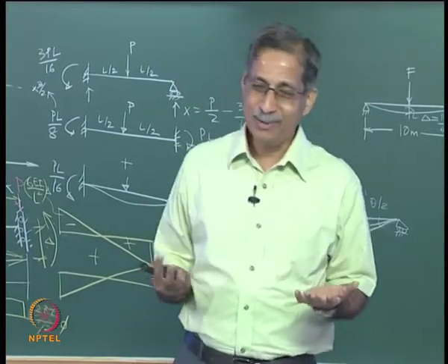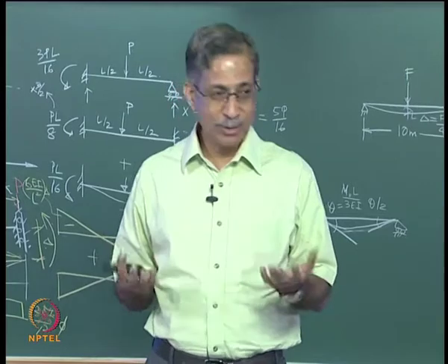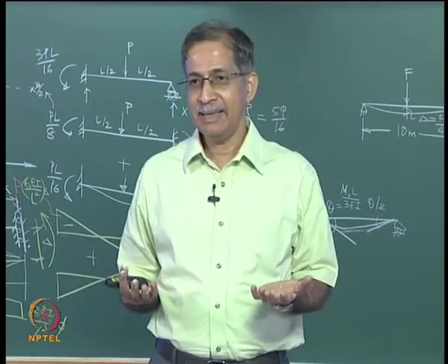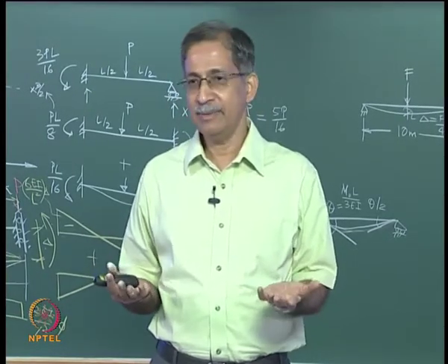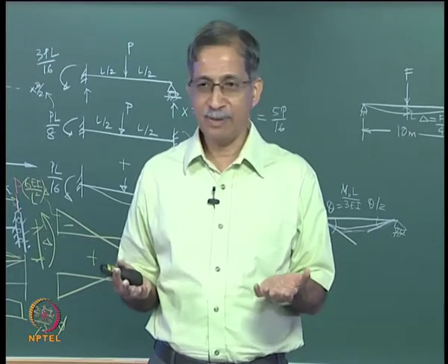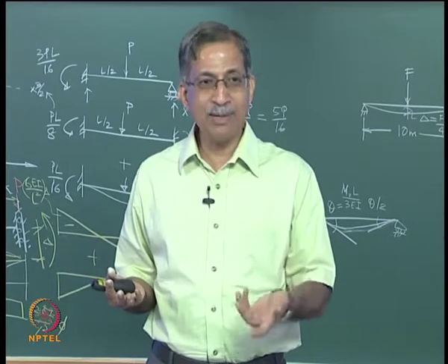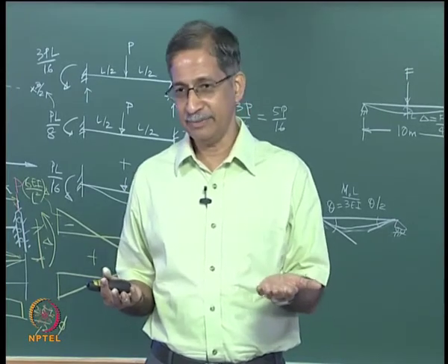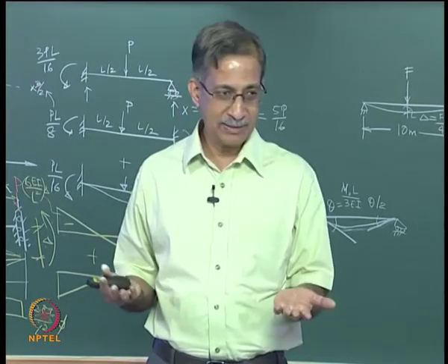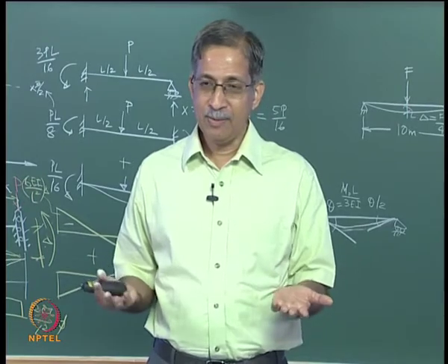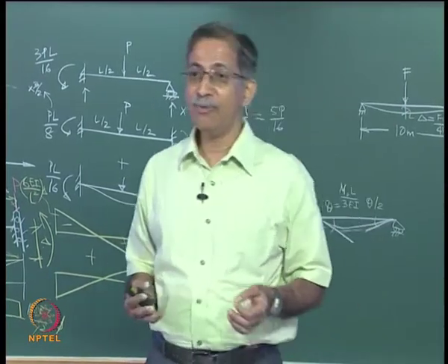Well, when you have a shallow foundation, isolated footings, and even sandy soil, where your safe bearing capacity is not very high, even a small movement there will release whatever moment you calculated. So that is one extreme. When do you model it as being fully fixed?